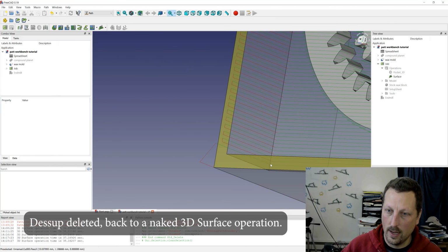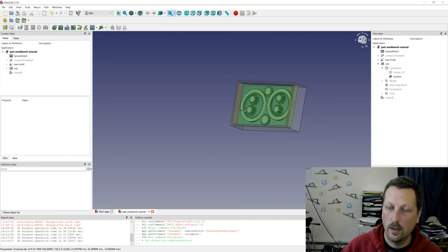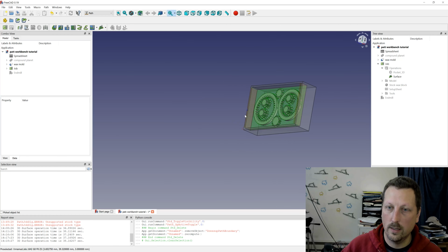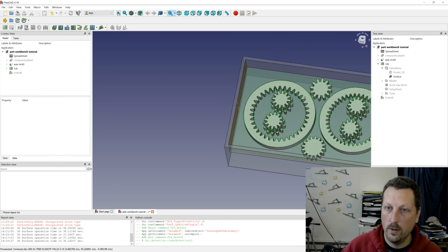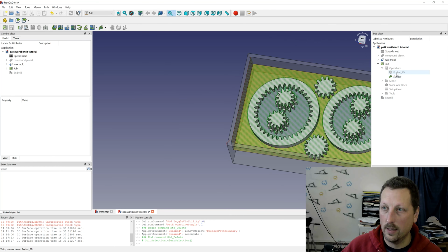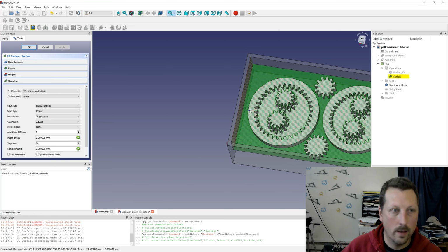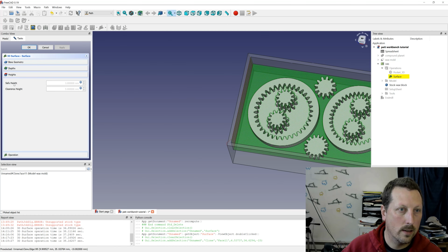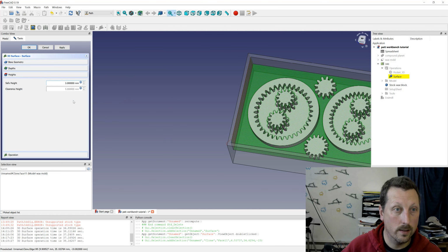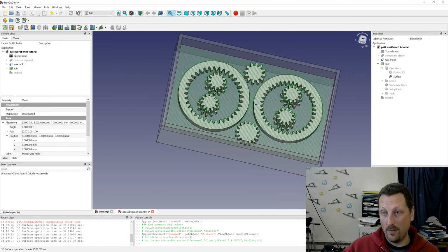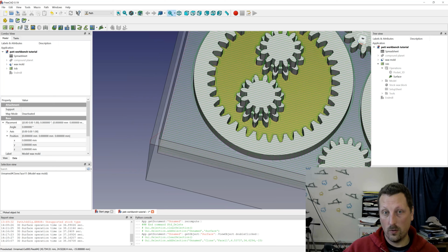It does the slow descent, and then it does a rapid climb, and then a slow descent. Oh, it does a rapid climb to the safe height, and then it does a slow descent. I wonder if we trick it into thinking the safe height is at the bottom. So we go heights, safe height here, -15. Okay. But yes, we have removed those hideous vertical walls.